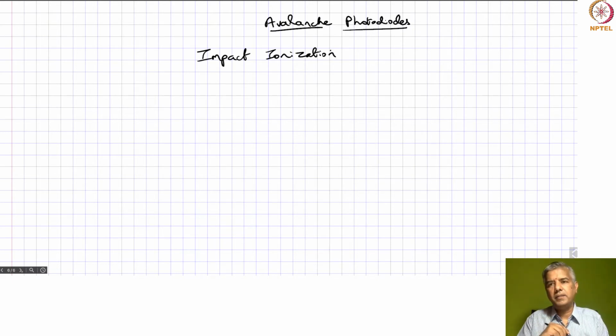Okay, and impact ionization essentially means that you can start with one electron and that actually generates an electron hole pair, right? And then, because the momentum has transferred to this new electron, that electron can still have enough momentum to generate secondary electron hole pairs, and so on, right? And similarly, if the hole is also moving with fairly high velocity, the hole can go and generate secondary electron hole pairs as well. So that could also participate in this impact ionization.